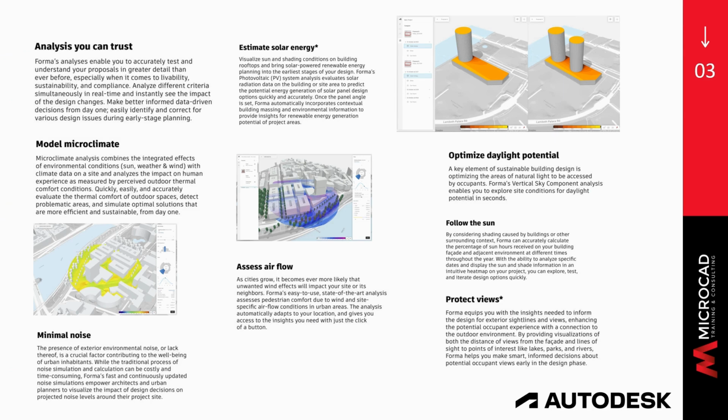The solar energy analysis is going to be a tool that estimates the building solar potential, right? So from your early design phase, you're going to be able to notice the impact of the sun, right? It's a feature that is going to help with roofs, facades, right? To see where is going to be the area that receives the most solar radiation, right? And you can estimate as well the potential electricity generation from solar panels, right? You know that the technology is right there, so you can take advantage of some of these tools to start at your early design.